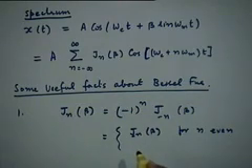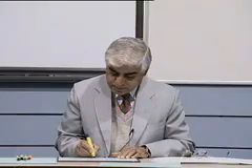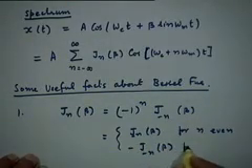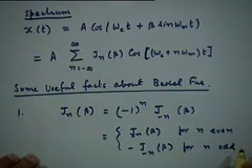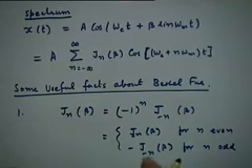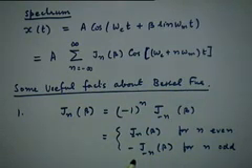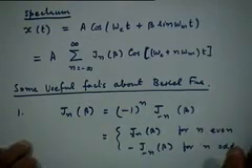and equal to minus of J minus n beta for n odd, right. So alternate coefficients on the positive and negative side are symmetrical but opposite in sign, right. So J1 beta and J minus 1 beta have opposite signs, but J2 beta and J minus 2 beta have the same sign, right, and so on and so forth. So that's one interesting property of these Bessel functions.